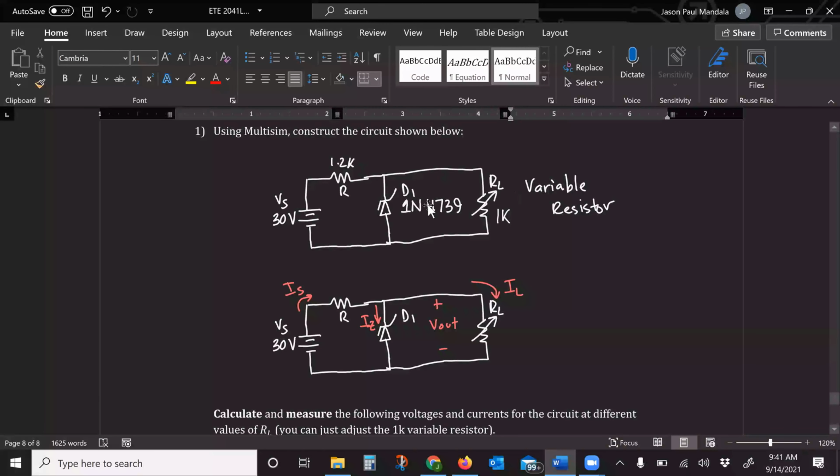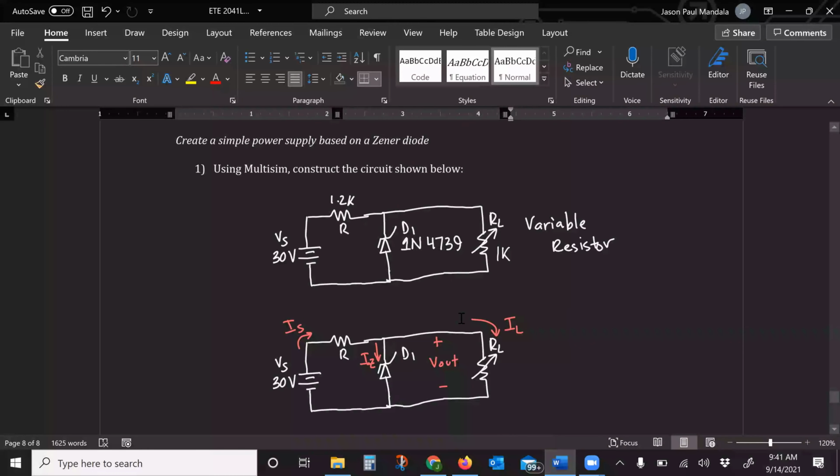So if you try to set a voltage that's larger than VZ, then the diode will turn on. Right? We talked about how we use the voltage divider to calculate the initial voltage, to calculate if the diode should be on or not. If it's on, then in this case, the Zener diode will drop exactly 9.1 volts. If it's off, then the voltage will be set by whatever the voltage divider equation gives you. And we also showed exactly what level of resistance would cause it to be on or off. So let's just reiterate that calculation real quick.